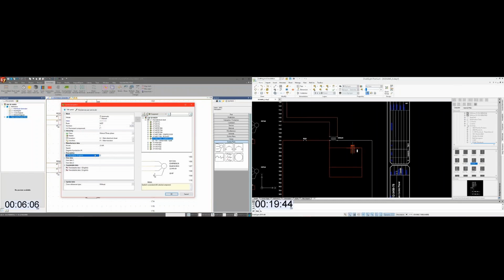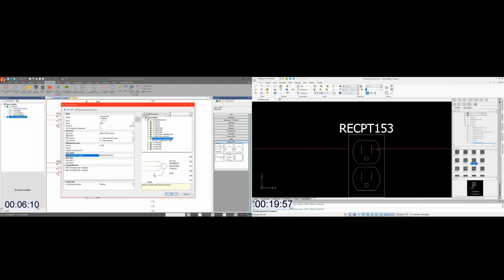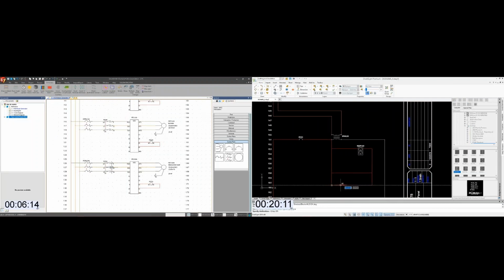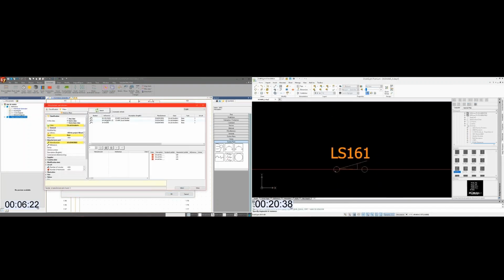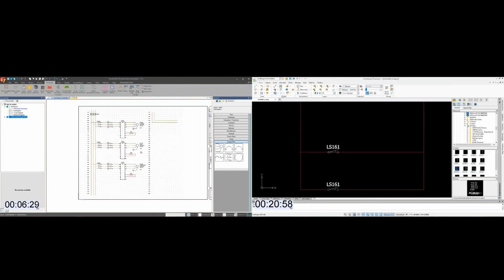Over here, I'm still working on changing some of the differences between these motor circuits that I've copied and pasted, but again, I don't have to worry about the tagging schemes on any of these. I'm driving all the metadata from my library. So 6 minutes in, and I'm making good progress, not only because the circuit's created and the design's coming along, but all that, again, as I'm going to drive this home, all the metadata behind.